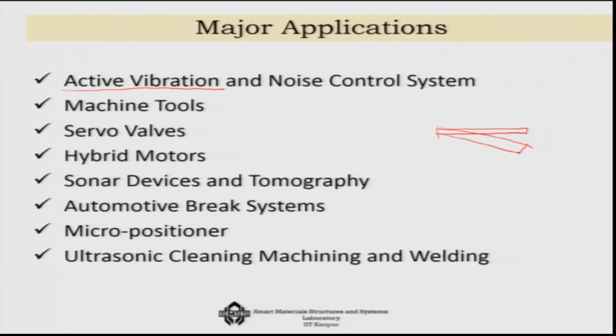I want to control this for various reasons, like structural purposes, comfort, etc. Now, suppose I am using a magnetostrictive material and I have a coil around it. Whenever it is expanding, I can give a compressive stress, so that it is forced to go back to its neutral situation. In the other direction also I can do the same thing. That is how active vibration control happens.